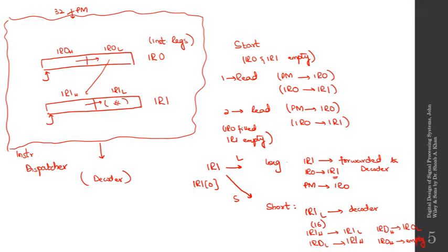At this point, when we have executed only a single short instruction, we cannot call upon the next instruction from the program memory, because only 16 bits are currently available that can be written. Whereas the bus that's carrying data from the program memory to this register is 32 bits wide. It means that at every read we'll always get a 32-bit instruction.